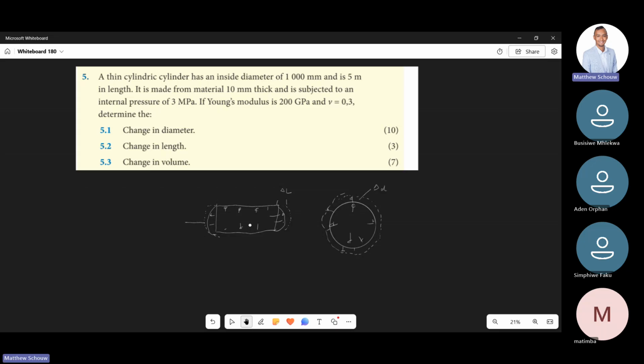I can't recall the pressures according to the standard, but you normally test at maybe 1.5 times the design pressure. Especially with thin stainless steel plate, it will bulge up and actually increase in size. So what we're looking at now is the strains, or rather the change in length and strains due to this pressure. I hope that's clear to everyone.